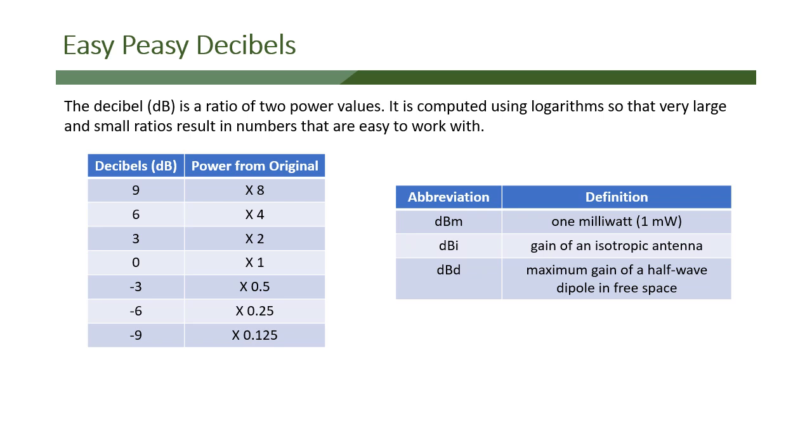So somebody might be buying an antenna and it says, this antenna is $300 and it's got a gain of 4 dBi. That means it's got a gain that's 4 decibels bigger than the isotropic antenna. An isotropic antenna is an antenna in an ideal condition in free space. It's floating in an imaginary world where nothing is near it and nothing can interfere. It's the ideal condition antenna. And so that's just a way of comparing one antenna to another.